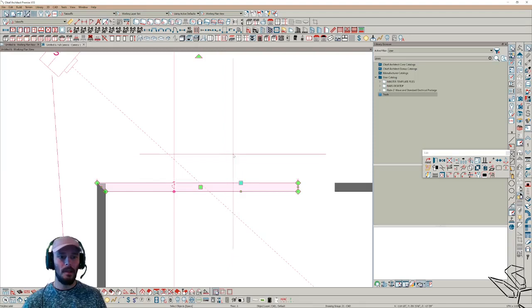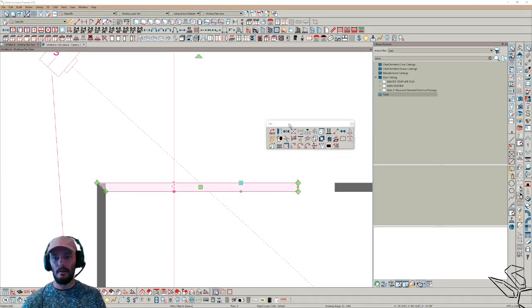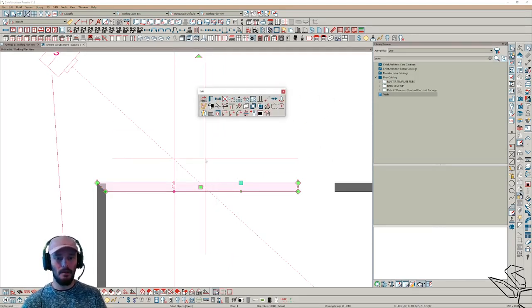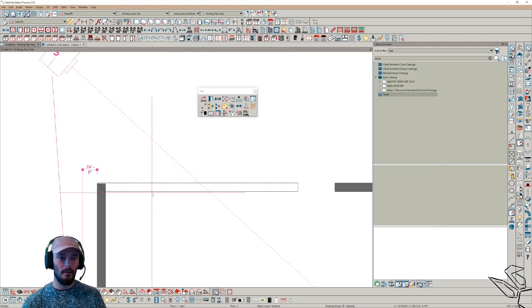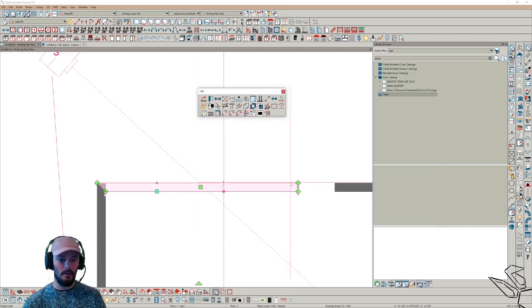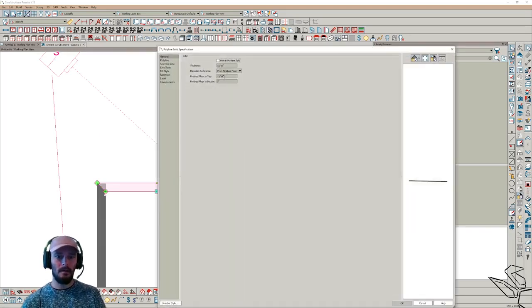Next, let's duplicate this in place. Let's move my edit bar here, but I'm going to use my mouse to do this. Duplicate, paste hold position. There we go. I have a second copy now. Open this up, and this one is going to remain that same thickness. Or maybe not. Let's make it 3/4 of an inch. We'll make that top piece 3/4 of an inch.